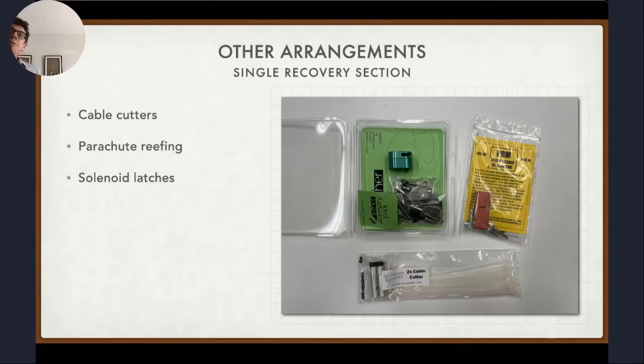Above 50,000 feet, there's two issues. One is how do you detect apogee, and the other is how do you protect your charges. There's probably a longer discussion here, but the short answer is black powder is designed to function when there's a reasonable amount of atmospheric oxygen. When you get higher in the atmosphere, there's less oxygen. So if you're going to use a black powder charge at higher altitudes, you either need to make sure the charge is sealed fully so that you carry the ground level oxygen load up with you and it doesn't escape at the lower pressures of the higher altitudes.